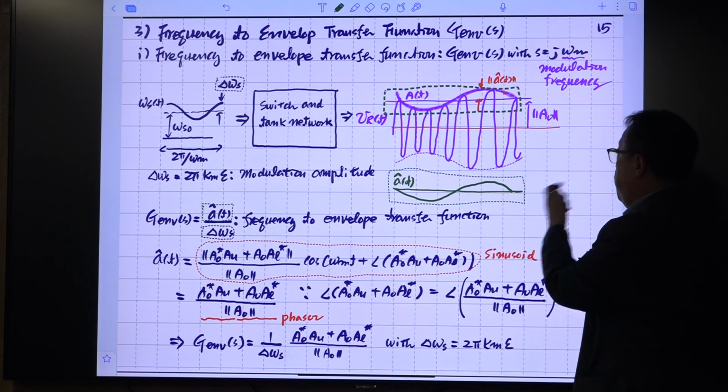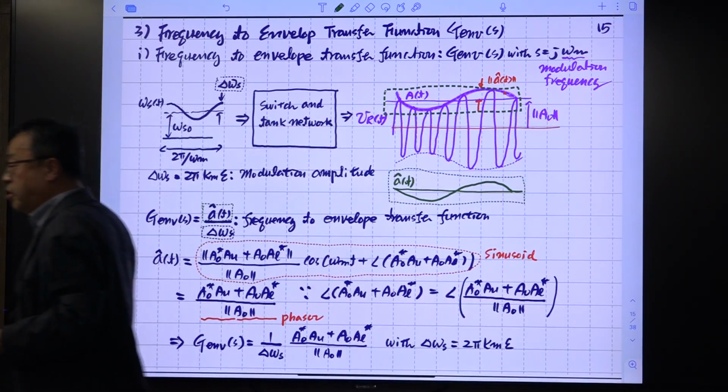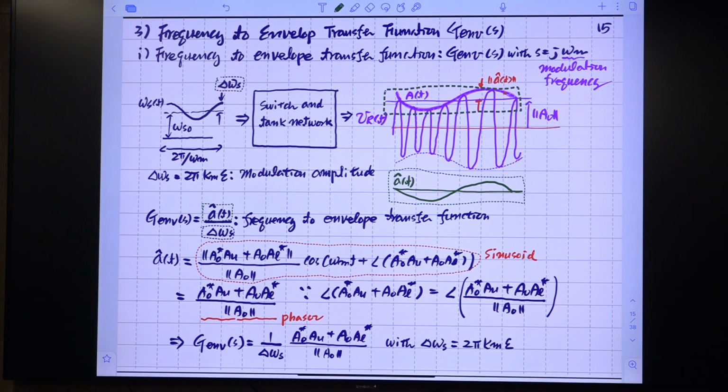So if we find this, then the analysis of the resonant converter is done, because it characterizes the inverter path dynamics, and this low pass filter dynamics is extremely simple, because you have the connection between this rectified sinusoid and the average value, pi divided by 2 or something, very simple thing.